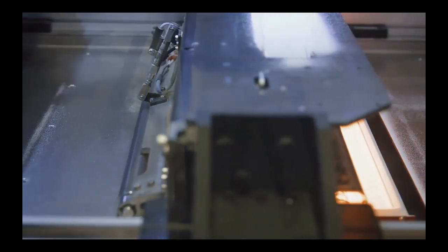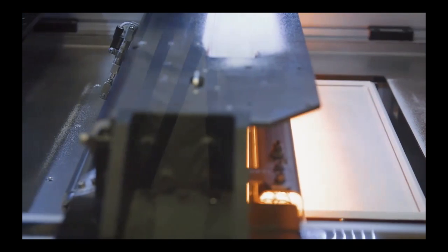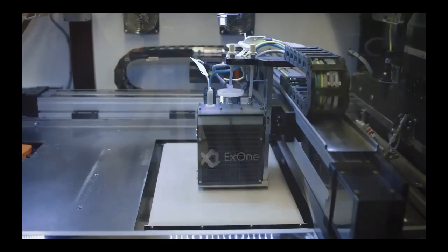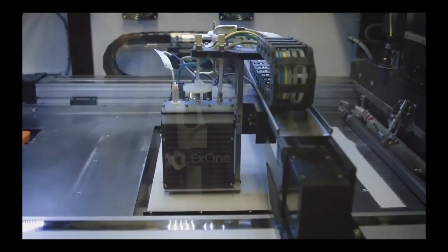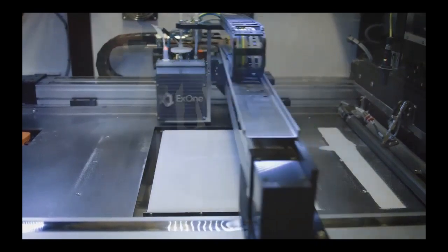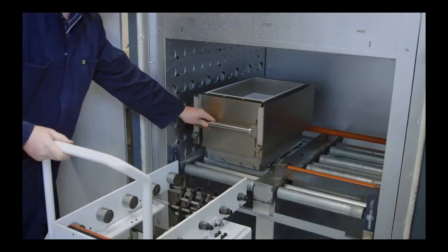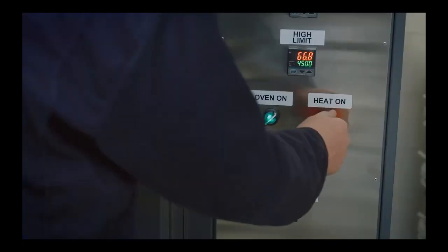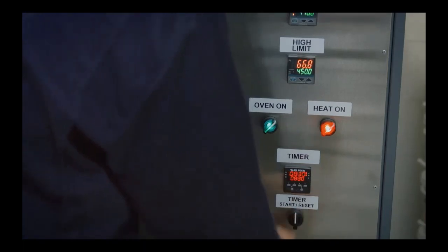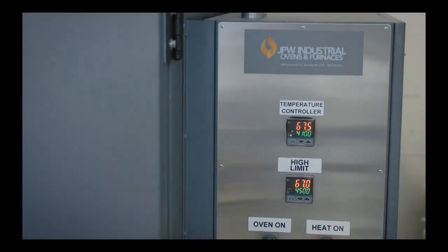Before moving on to the next layer, the solvent contained in the binder is evaporated by an incandescent lamp. The powder bed is then lowered and a new powder layer is deposited. Therefore, the production takes place in a series of steps that build the part layer by layer. When the cycle is completed, the binder is cured by placing the container in a furnace. The temperature and time depend on the type of binder employed during printing.